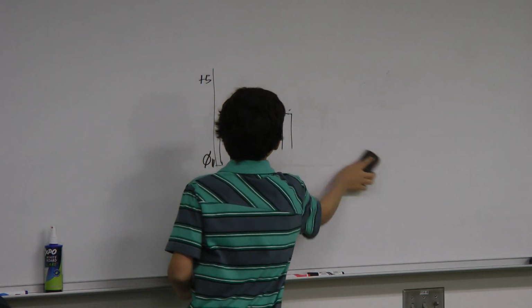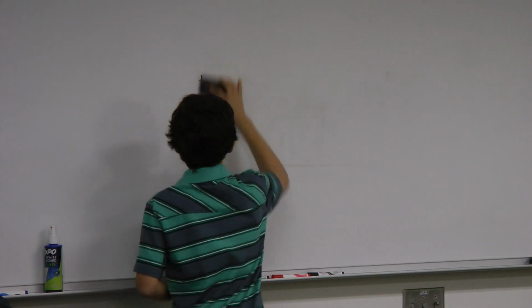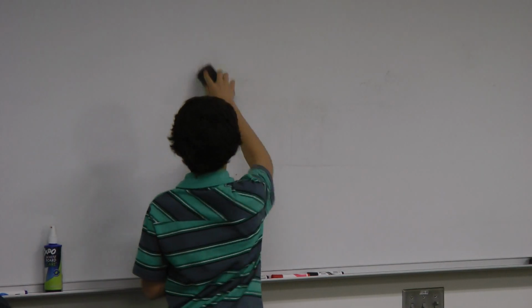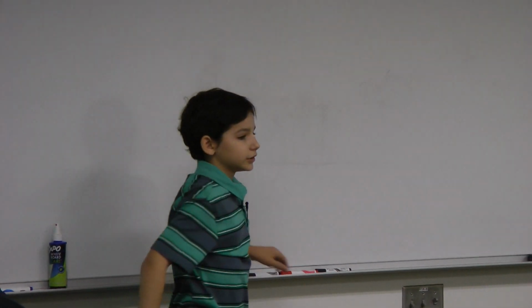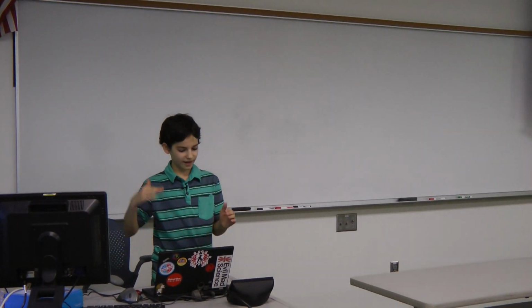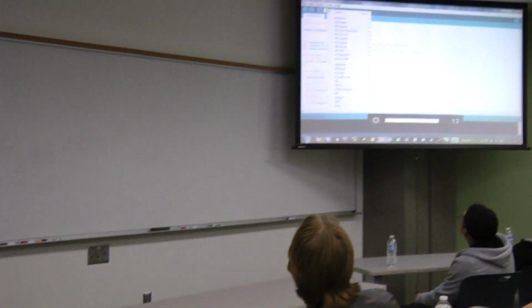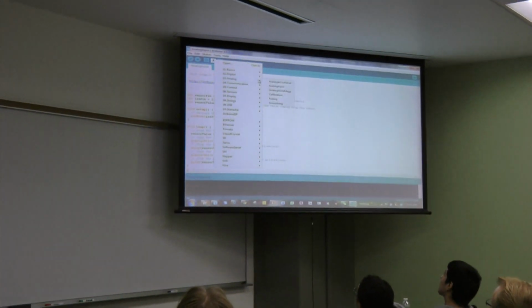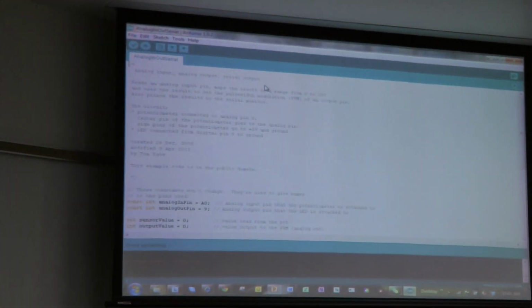So what we'll do is, the Arduino actually has a built-in 8-bit PWM. That means you can vary the time on versus time off, and it has 8-bit resolution. On our computer, we'll go up to Open, and go to Analog and Analog In-Out Serial.